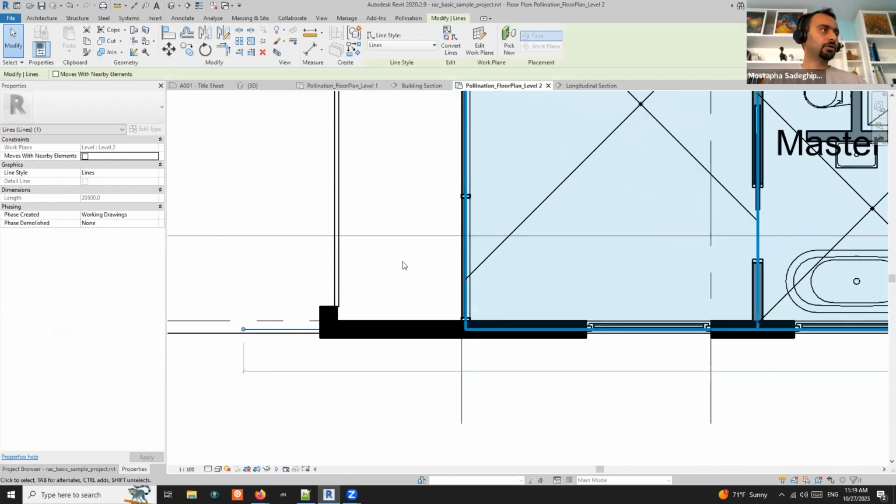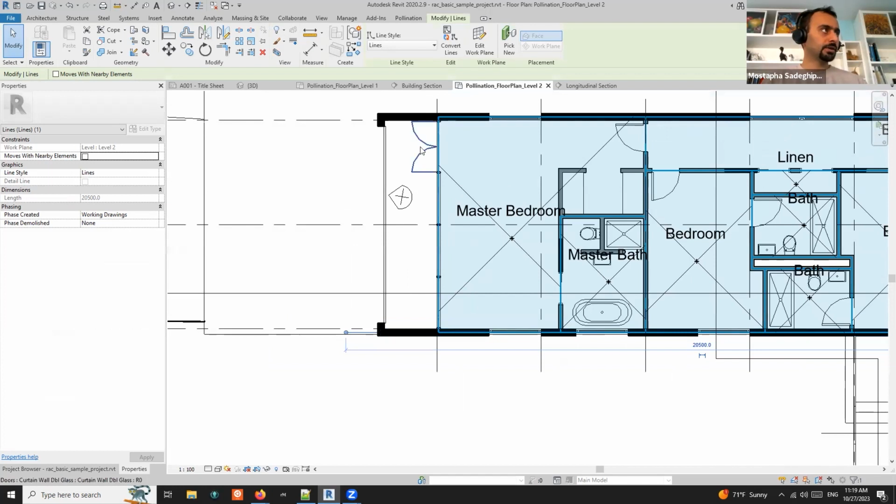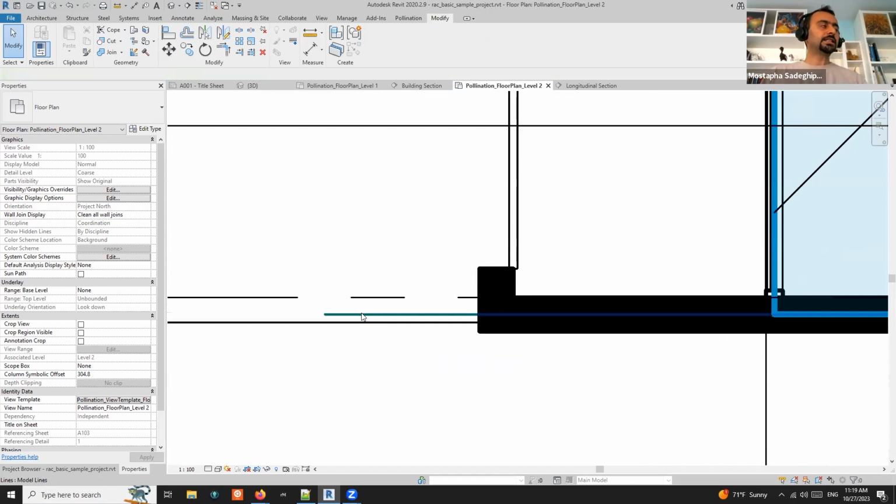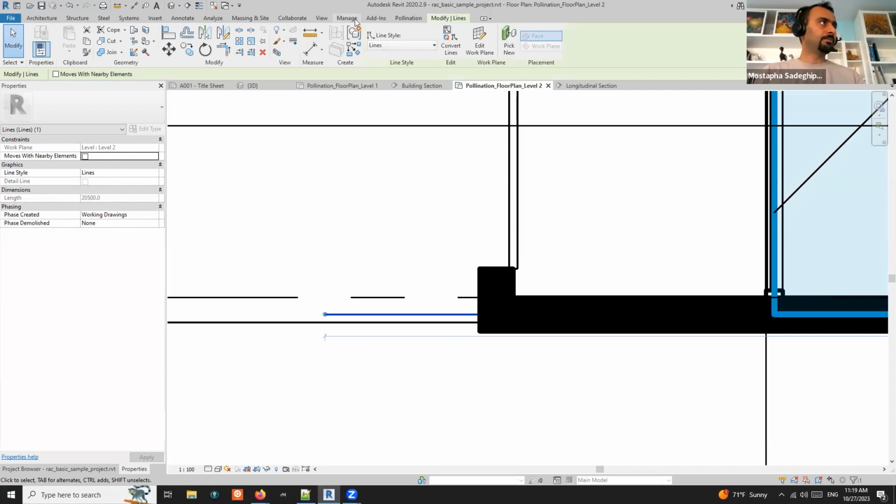If you know Revit and you feel comfortable, you can also draw another line here. I'm not going to do it because, the way the workshop is set up, I don't want people to get confused about drawing a line. Now, and this is part of how Pollination uses these alignment lines, again, this is an area that I think we can improve a lot. But for now, what you need to do is select this line and go under Manage.